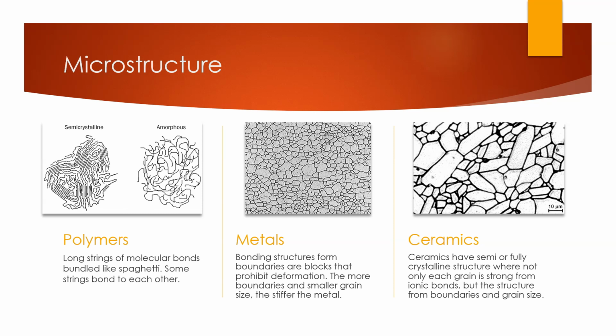Ceramics microstructure is very crystalline and defined. To the same point as with the metals, ceramics typically have more grain boundaries and in longer shapes because the ionic bond clusters are less continuous due to the amount of bond energy they require. More grain boundaries as well as smaller grain sizes mean more brittle. There are some ceramics that have an amorphous structure like plastics do, namely borosilicate glass, which makes them easier to process, but this is less common.